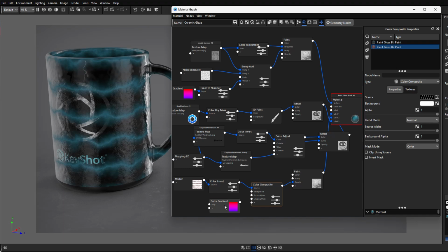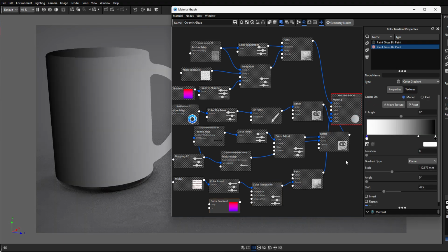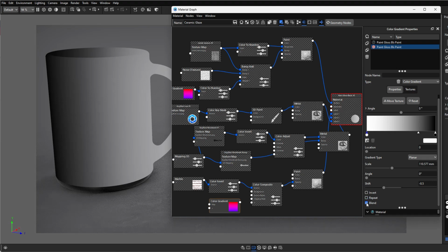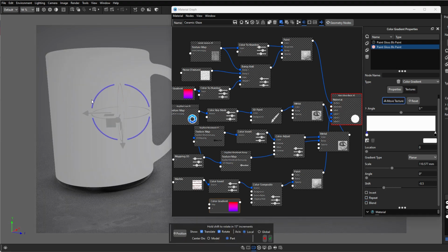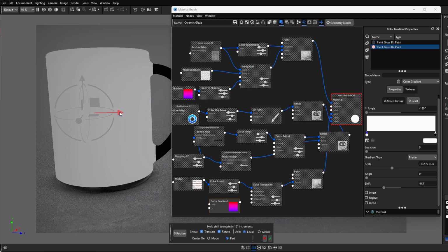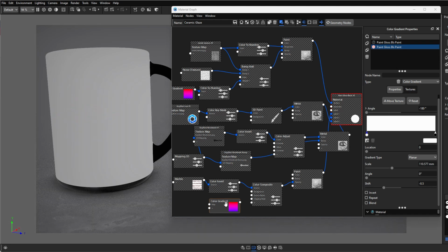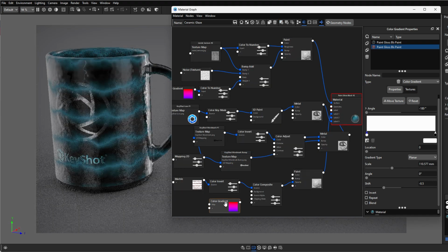First of all, I'm just going to hit C on my keyboard so I can see what it's doing, and then manipulate whereabouts I want it to be. Now I don't want there to be a blend. I want to go straight from white to black in this case. I'm going to then move the texture around and manipulate the positioning of it so that just the handle has that black colouring on it, and then the main body of the mug is white. So when I'm happy with the position, hit the green tick and then C on my keyboard to disable the preview.